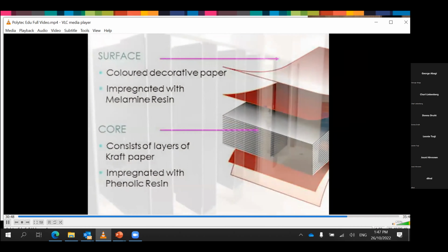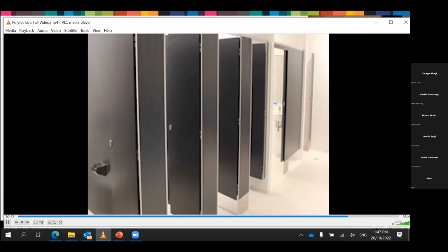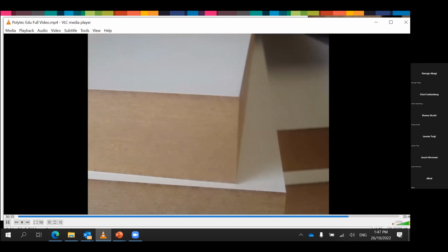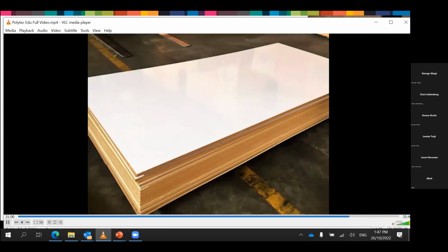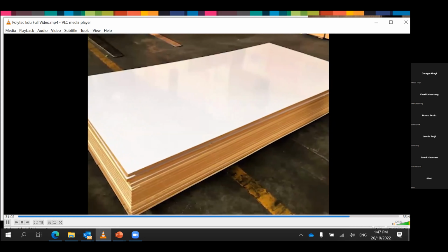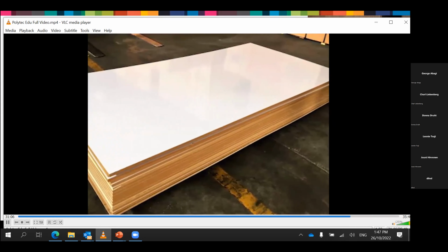For more colour or texture variety in a medium impact resistant range of options, MDF 32mm thick, hand laminated with a wide range of laminates can be used. Sheet size is important. Optimal is 3,660 by 1,830mm.